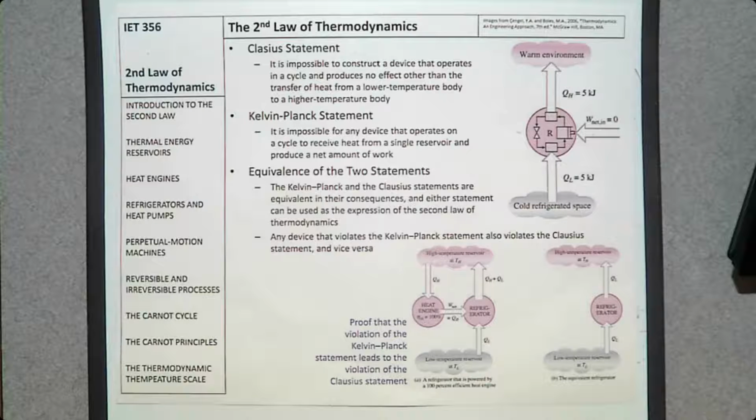If you convert every single thermal energy of the fossil fuel to work, that means the temperature of the working fluid should be what? 0 Kelvin. Because you are converting 100% of heat into electricity. Then what is the thermal energy left over? Nothing. What is the temperature when there is no thermal energy? 0 Kelvin. So at the exit of the turbine, the temperature should be minus 273 degrees Celsius. Can you do that? No.